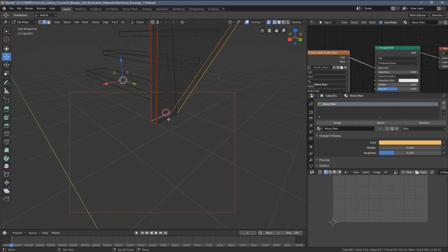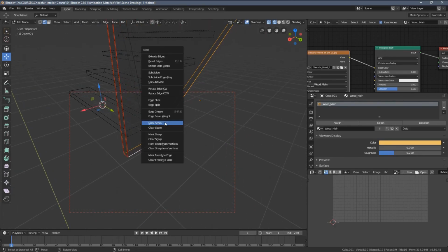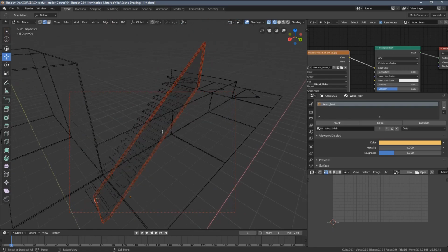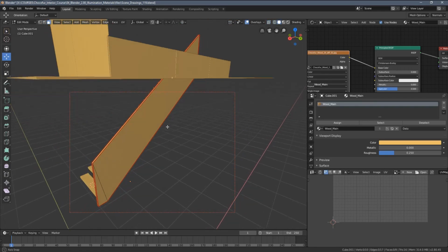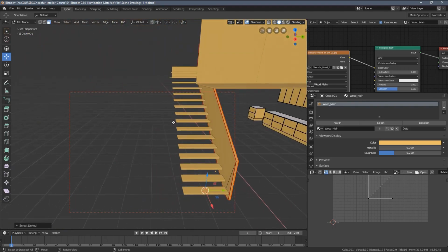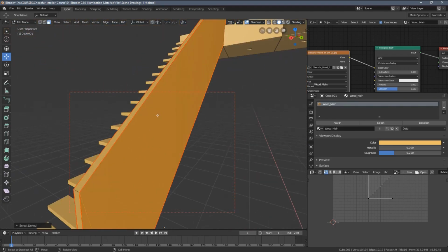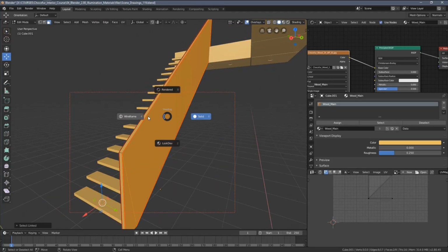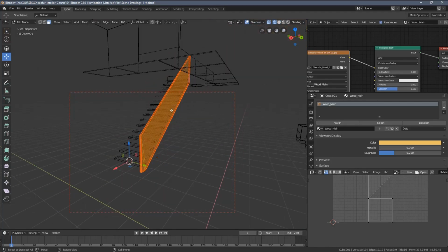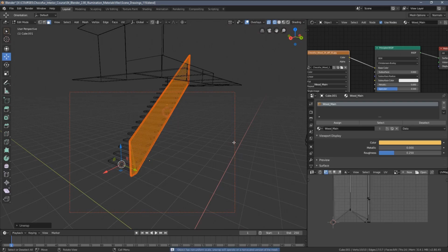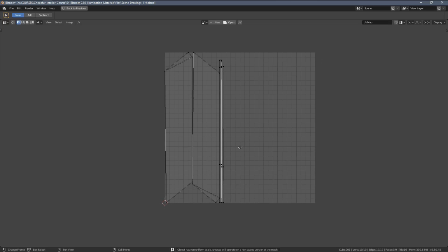What it does is it actually separates those two huge side faces one from another. As you can see, when I'm hovering my cursor and pressing L key, they are selected separately. So let's select everything, press U and unwrap. This is the UV layout we have now available.